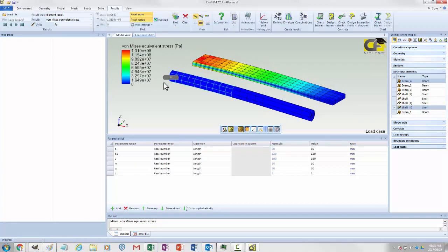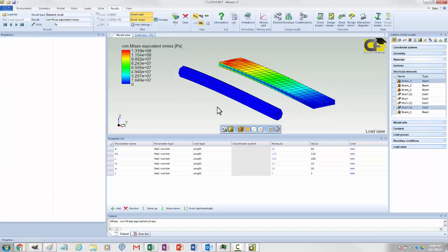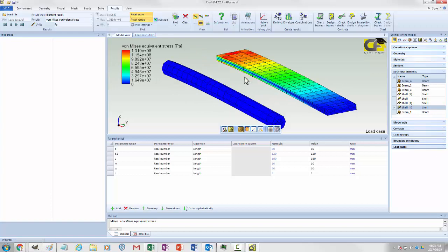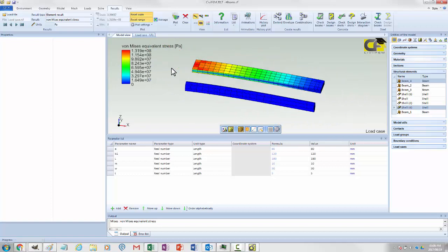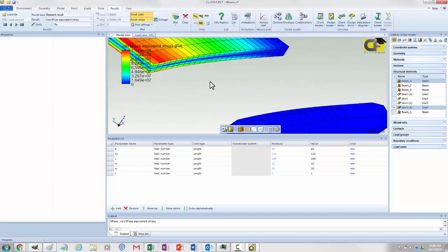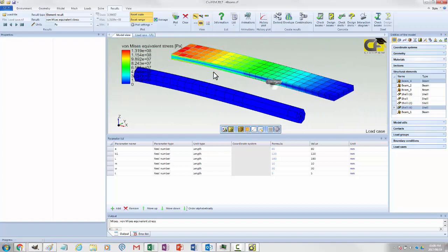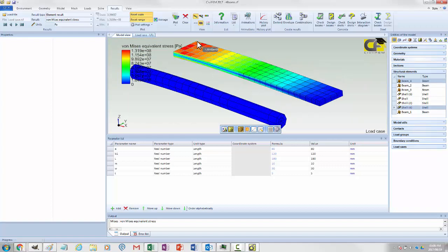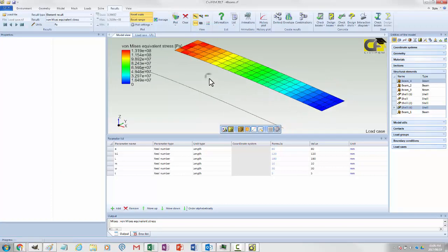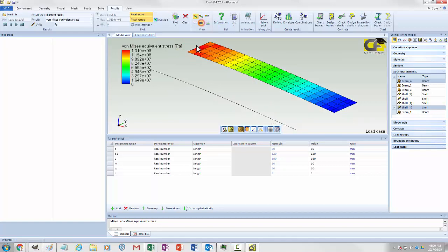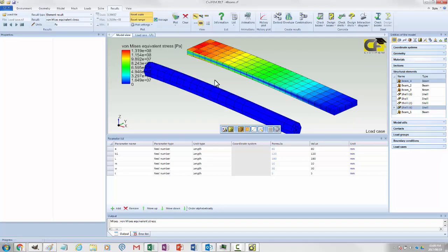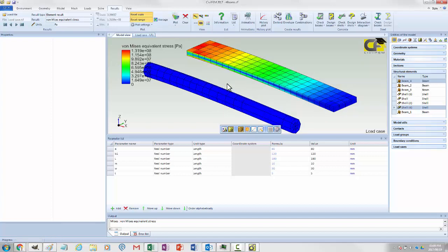We obviously don't see any values for the beam elements, but we can see that very nicely for the shell elements, and we can see the through thickness stress changes as well for these shell elements that are actually only flat elements like this, but through a thickness property actually provides us with an additional dimension on these elements. All right, so that concludes the second session where we created the beam represented by shell elements.